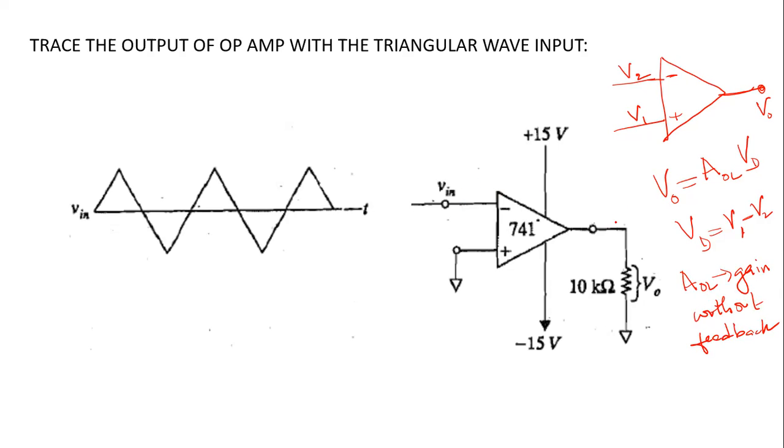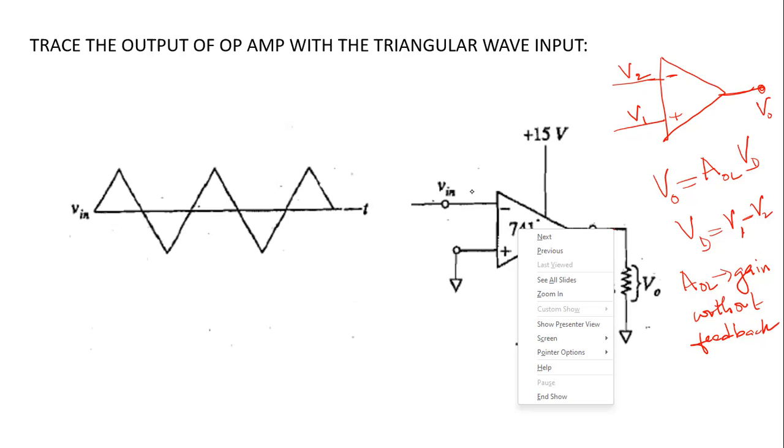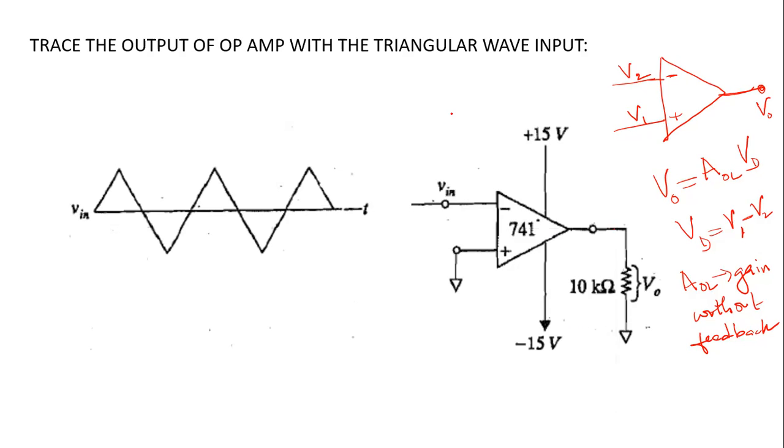Suppose through a certain circuit, you connect the output signal from pin number 6, your V0, back to the input signal, then that gives you your circuit with feedback. So it feeds back a certain portion of your output voltage to your input signal. That is called closed loop. Closed loop means you're connecting output to input.